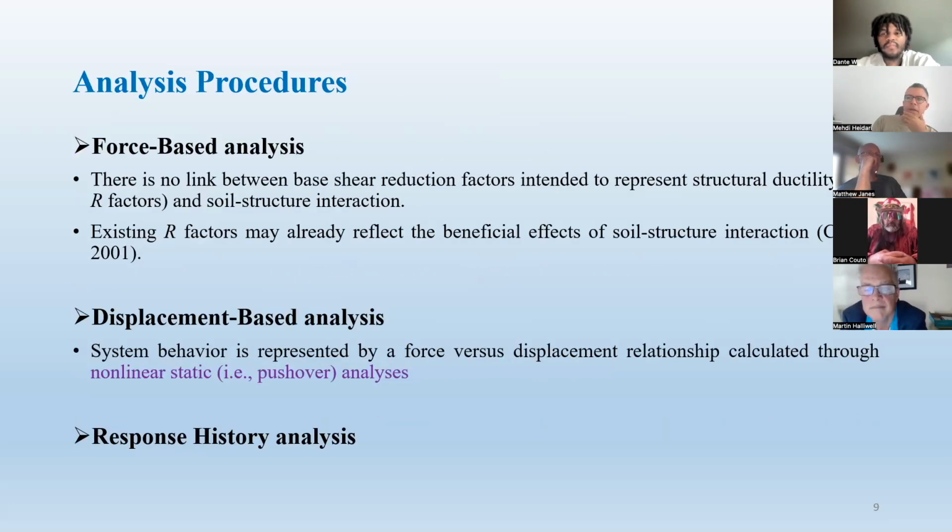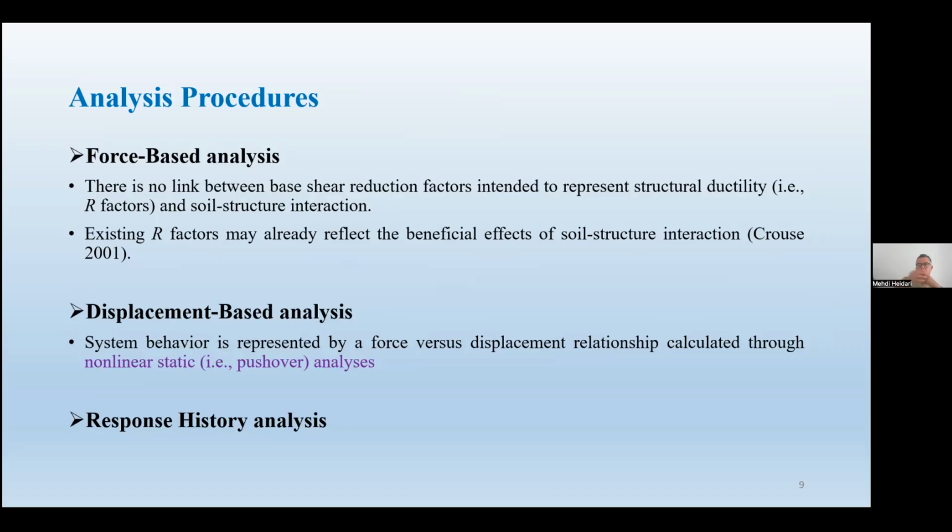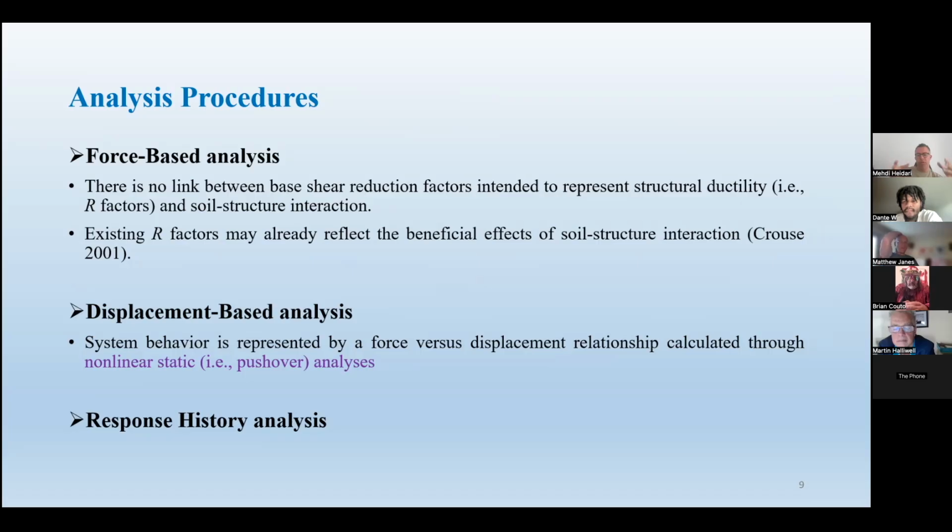We have different types of analysis, as you can see: force-based, displacement-based, response history analysis. For that particular example, for piles, most of the time, especially with tools like SAP or CSI tools, this Winkler model, they go with force-based, but probably the displacement-based approach might be a better option.